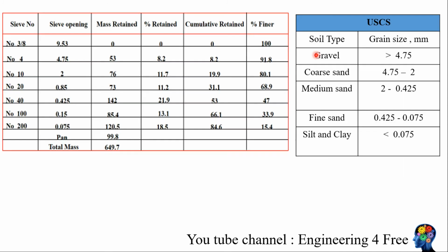The next task is to determine the percentage of fine-grained soils, which are the percentage of silt and clay, the percentage of gravel, the percentage of sand, and the percentage of coarse sand, medium sand, and fine sand. To calculate the percentage of silt and clay, we will refer to the table on the right hand side.